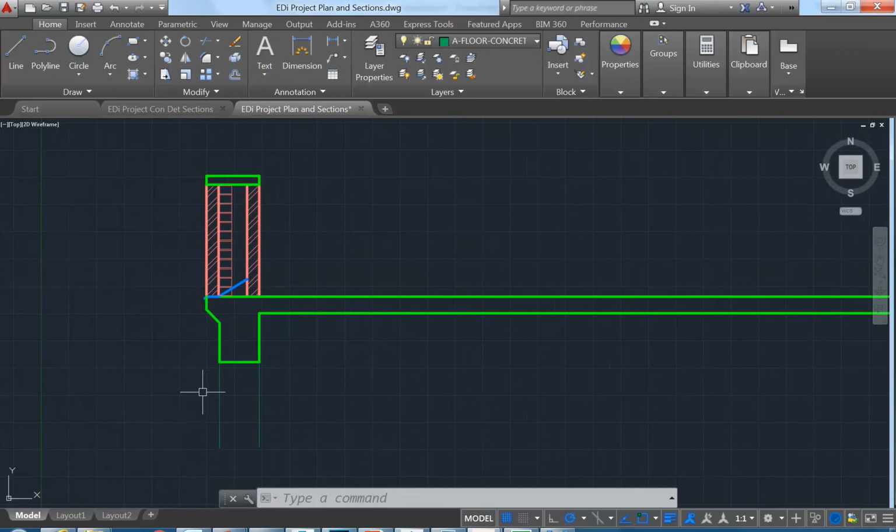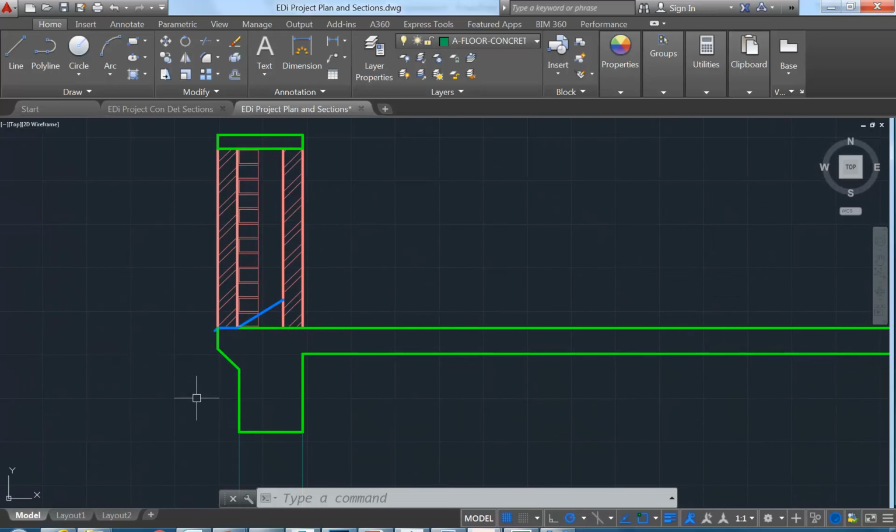Right, so can you see how much clearer that is? We can see that's with a lighter line weight behind this part, the beam and the floor that are being cut. And before long you just will read that naturally. Anything with a lighter line weight, you'll automatically think that's behind the things that are being cut, which are in the foreground. Even though, of course, in reality that's not the way it would look. If you cut through it, the line weight, of course, wouldn't be there. But again, before long you just think the line weight naturally is heavy when something is cut. So that's the way you want to be reading your drawings, and hopefully that reads clearly as a column.